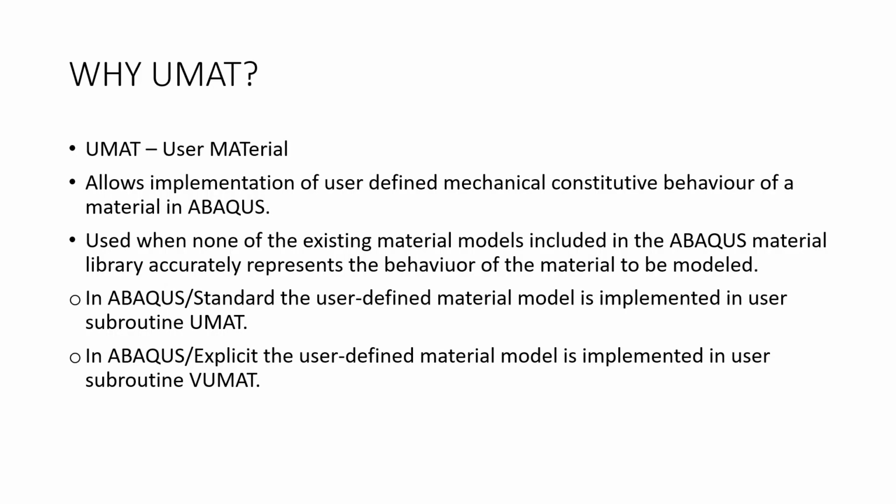In ABAQUS Standard, the user defined material model is implemented in UMAT, while in the case of ABAQUS Explicit, the subroutine used is called VUMAT. We will be majorly dealing only with UMAT, since we are going to deal only with ABAQUS Standard.